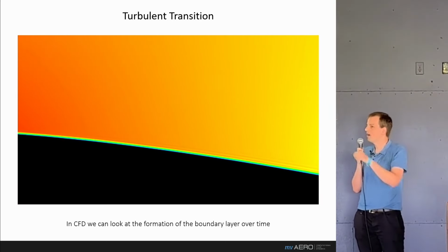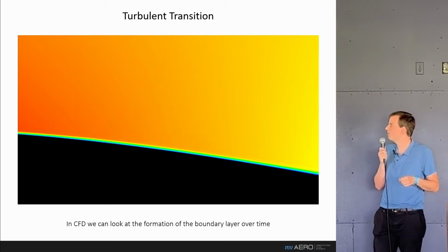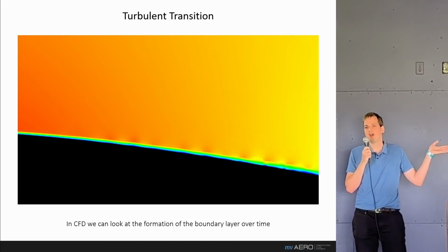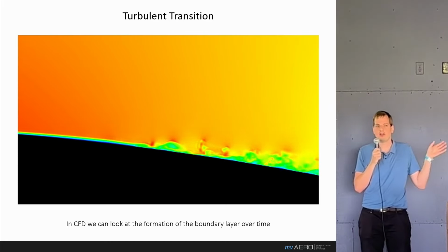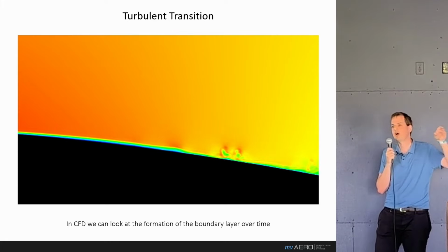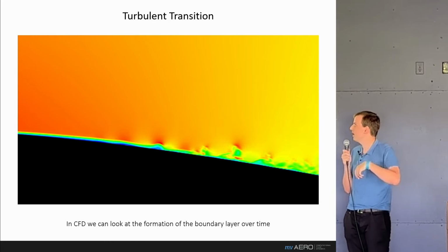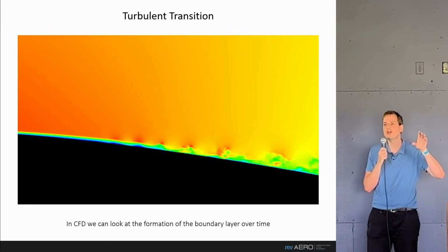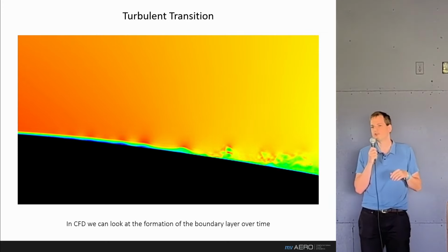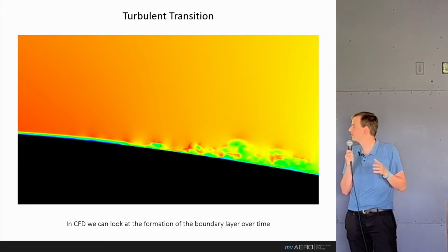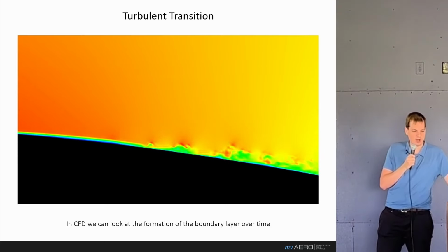And as you can see, the boundary layer started off thin everywhere. It's only as time moves on that this boundary layer starts to pile up. All the friction that was created at the front of the wing starts to pile up towards the back. The boundary layer then becomes too thick, starts to oscillate, and finally breaks down into a fully turbulent boundary layer.